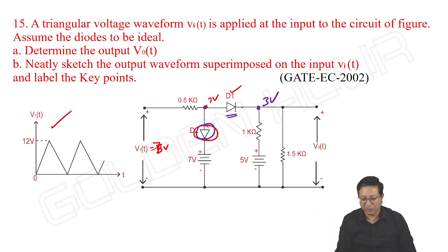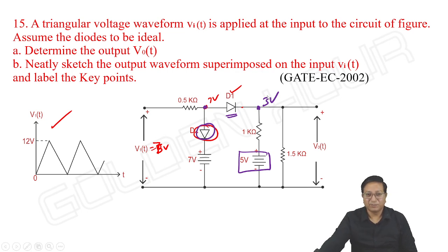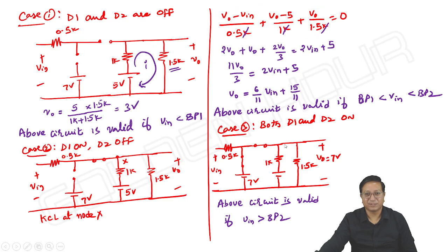I need not go up to 5 volts because the voltage here is only 3. That's the interesting point in this problem. Okay, we'll check it. Input is 4 volts, then how can D1 conduct, because its anode is going to 4 and the cathode is going towards 3? How can D1 be on? It is possible because of this 1.5 kilo ohms. That's the idea in this problem.